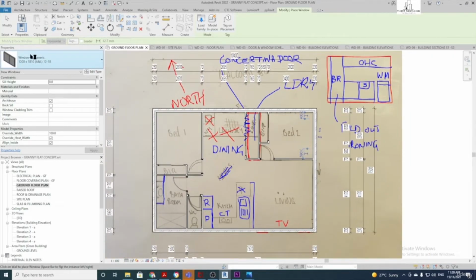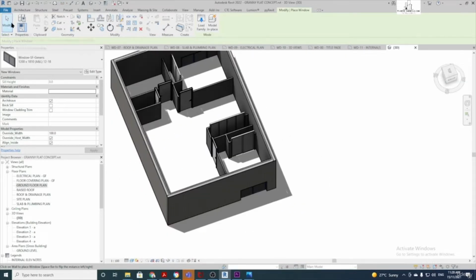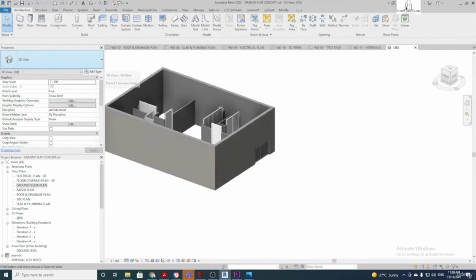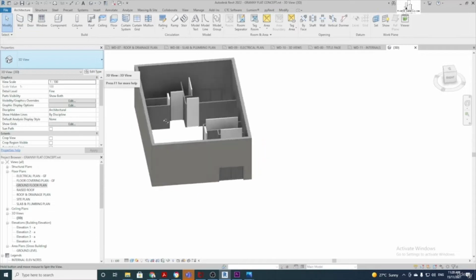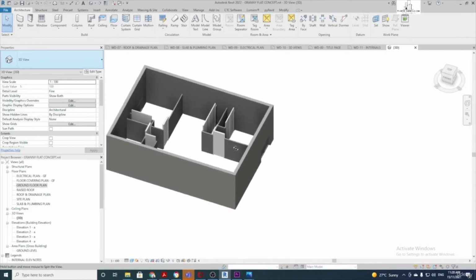And now we'll go up to our 3D view, so I'll show you where they're placed. So click up here, default 3D view, a little house, click on that, it'll bring up our 3D view. Click back onto this little cursor button, make sure we've got it selected, now we can navigate around, and we can see that our internal walls are the wrong height.